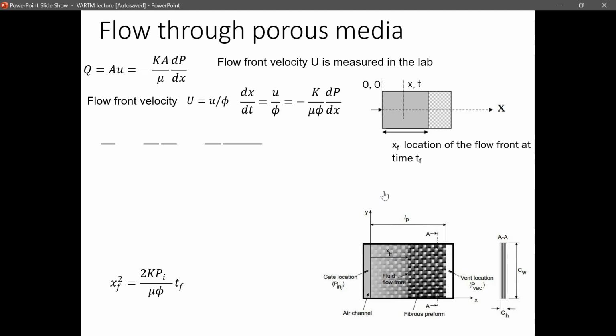So you are going to cut a very long fiber, and you're just going to see the flow front moving in the same direction at all times, right? And in the lab, you have to record this, and you're going to have a tape measure just beside your fabric. So you're going to know what is the location of your flow front, that resin front, at all times. And based on that, you can find the velocity and whatnot. But we're going to talk about it.